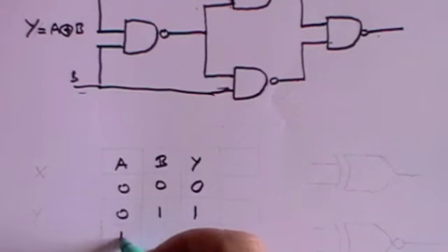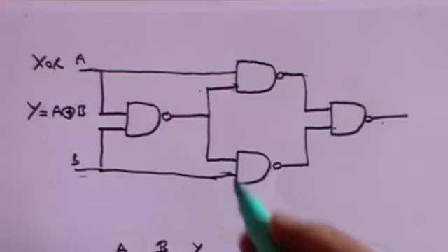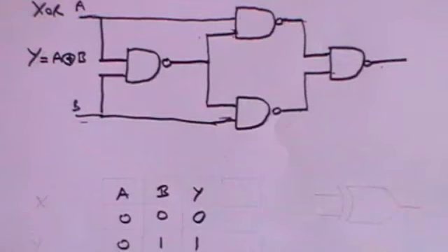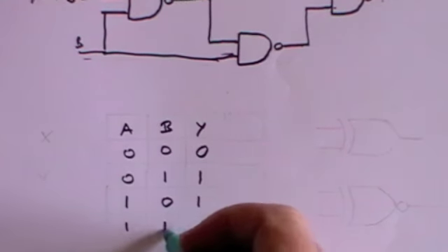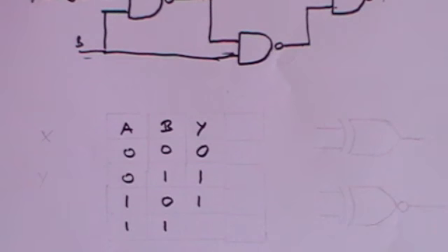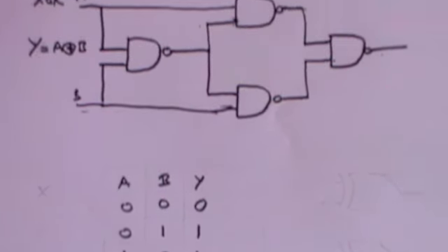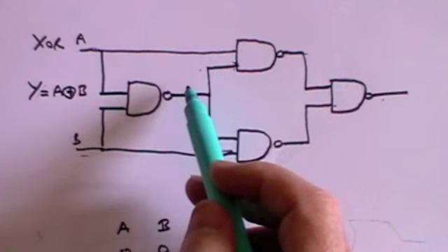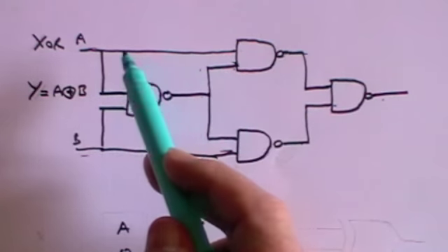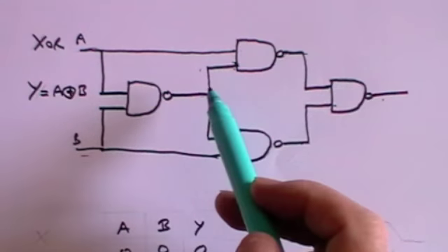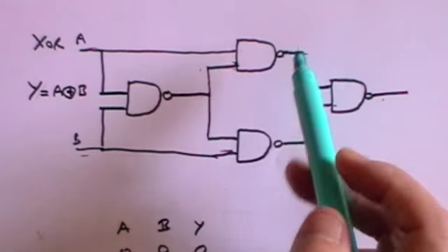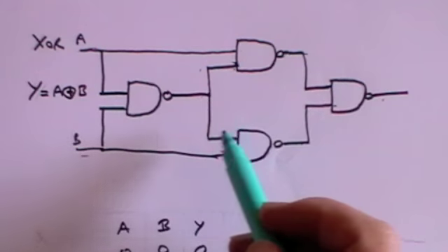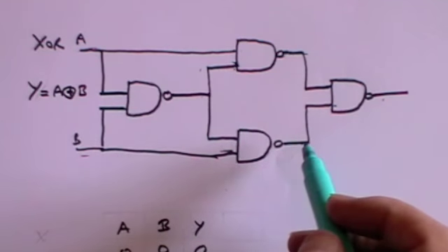If you do it the other way round, I think I don't need to talk you through it. It's obviously symmetrical. It's going to be exactly the same. So there is going to be a positive output coming out here. And the final set of situations is if both A and B have got positive inputs. Well, what's going to happen? 2 positive inputs coming in here will give you a 0 output because that's the consequence of a NAND gate. A positive input and a 0 input will give you a positive output. Same applies here. 0 out, positive, 0 out becomes 0 in plus the positive in gives you a positive out.